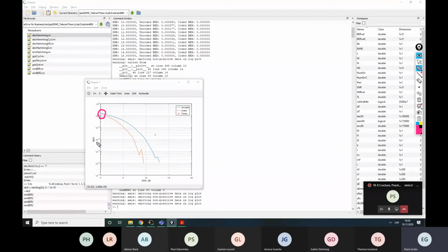As you can see also in this case, it didn't make it worse at the signal to noise ratio 0, but if we go to negative signal to noise ratio, meaning that we have stronger noise than signal, that would be the case. Then we would have it here. And one more thing, one student correctly said to me in his report that he found it maybe not clear, not obvious, that asymptotically we are approaching the value representing 0.5, meaning 50% error probability, not 100% probability. So meaning that if we have minus infinity signal to noise ratio, then BER would actually reach 0.5, not 1, 100%.